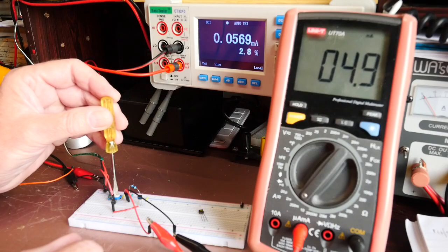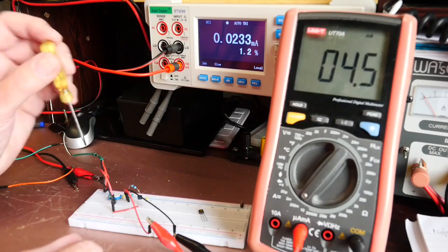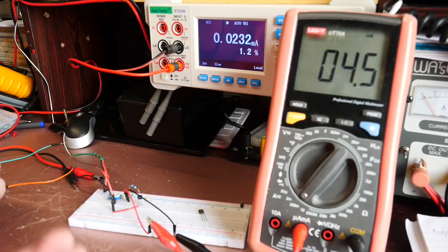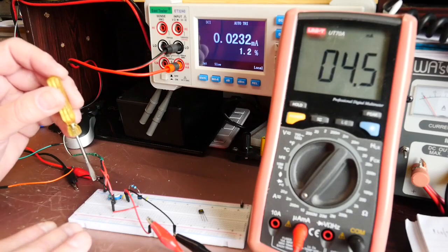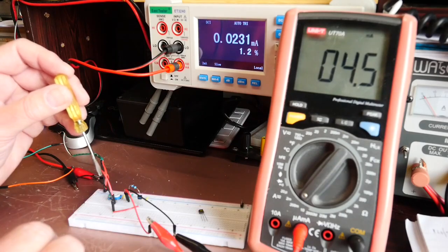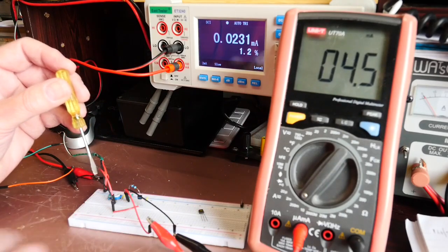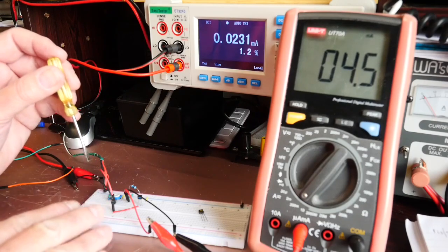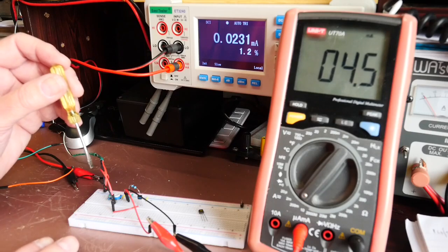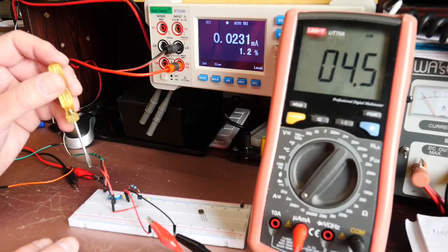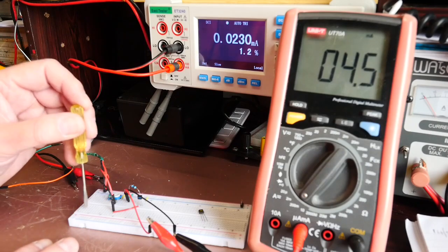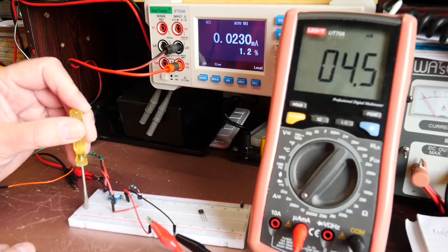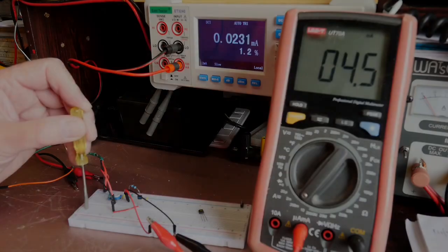And if I continue now, let's just see if we can get to a similar level for you. There, 0.45, and we're at 0.02 milliamps, so that has actually required even less base current to achieve pretty much the peak of the collector current. Again, I've graphed that, so let's now go and have a look at those graphs and see what we can say about those two transistors, the yellow and the blue.